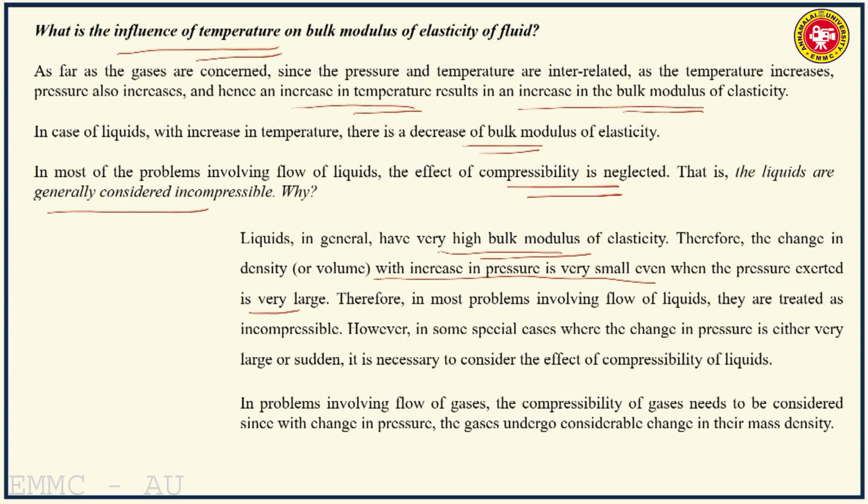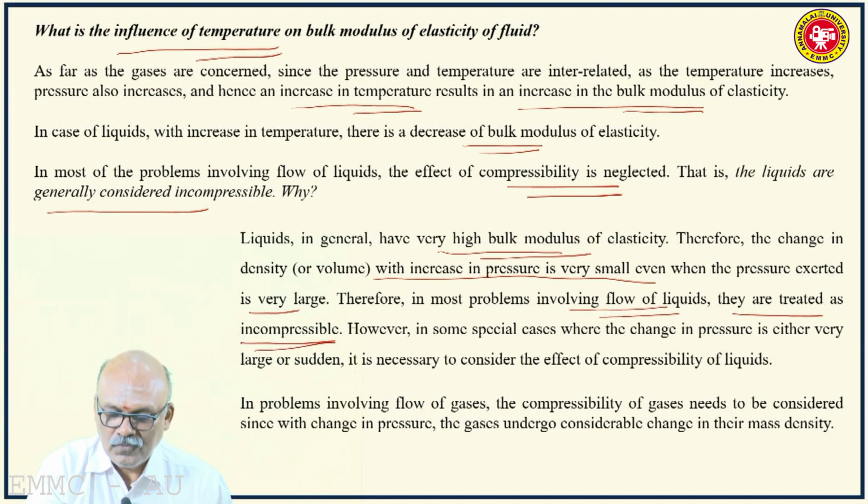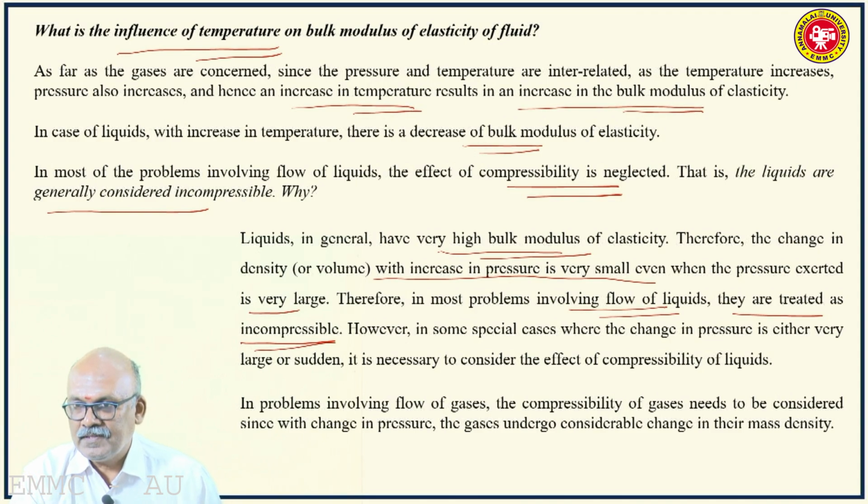So, there is no change in the volume or mass density even if you increase the pressure to a very large extent. The change in density or volume is very small in case of liquids. Whereas in case of gases, even for a slight variation in pressure, there is a huge change in the density or volume. Therefore, in most problems involving flow of liquids, they are treated incompressible. So, please note, liquids are incompressible, gases are highly compressible.